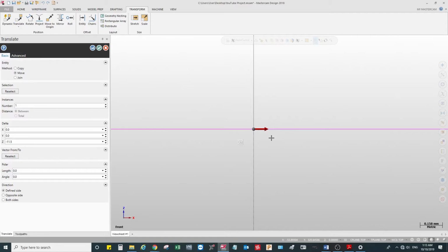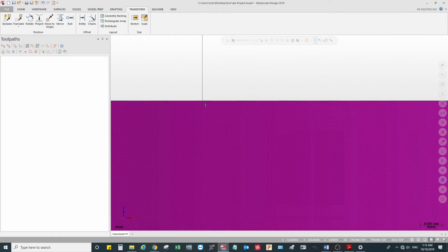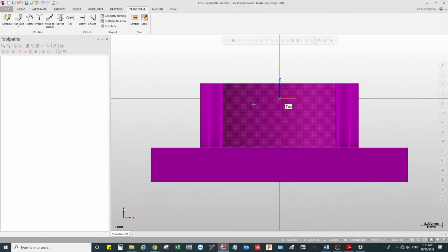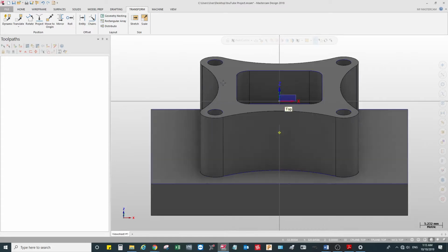When I'm giving the tool offsets on the CNC machine, I'm going to take the tool offsets from the top of the part. That is something you need to really think about before you start machining: what is the best, optimum way for you to do it, either use a top Z reference or a bottom Z reference. So I click on this OK button, then I click on fit, I click on zoom 80, and then I'm going to clear the colors.